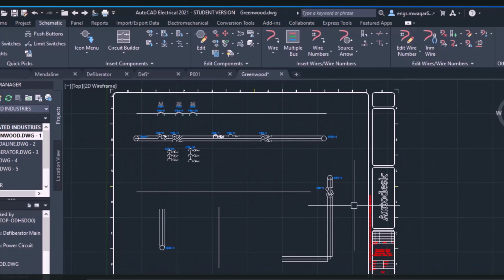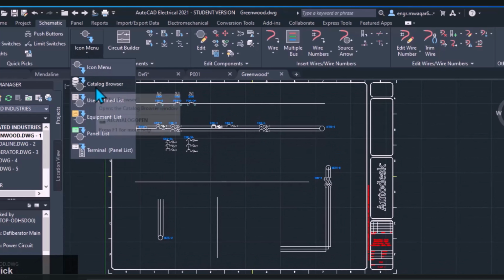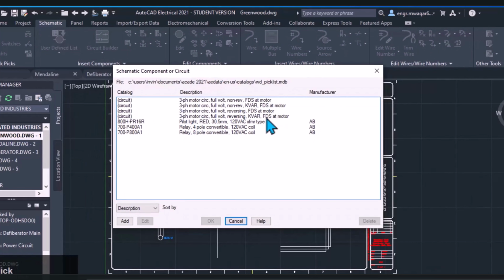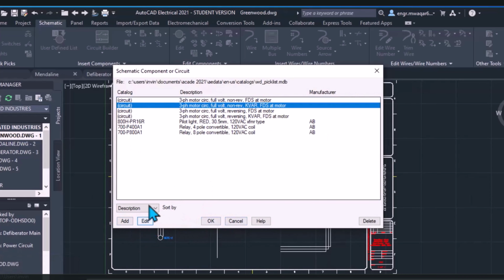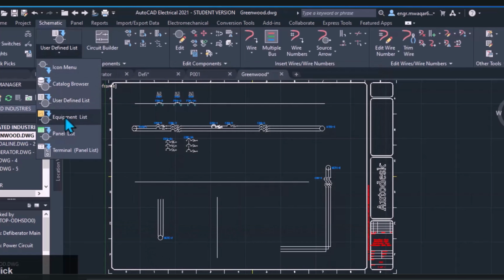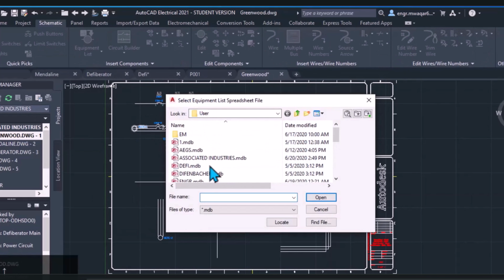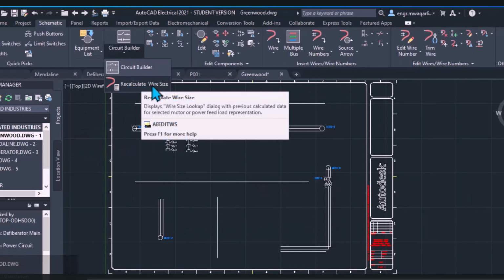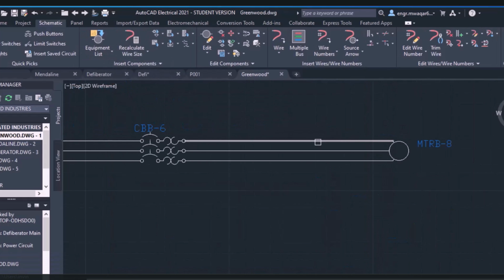Right. In schematic design, power inherently flows from the supply source toward the load. Okay. Visually, across the entire engineering world, that translates to flowing from left to right, or from top to bottom. So it's like reading a book. Exactly. If you place a motor pointing to the left, you are visually implying that power is flowing backward against the established convention. So it's actively stopping me from drawing something that might technically function, but would deeply confuse the next engineer who has to read the blueprint. Precisely. The software restricts your graphical freedom to guarantee your schematics are universally readable.